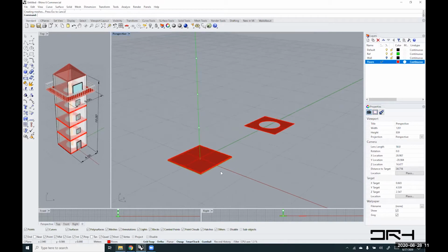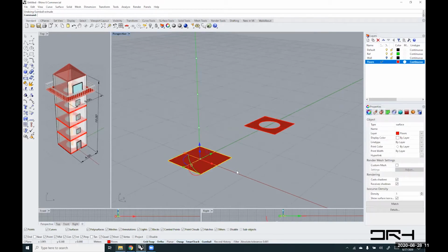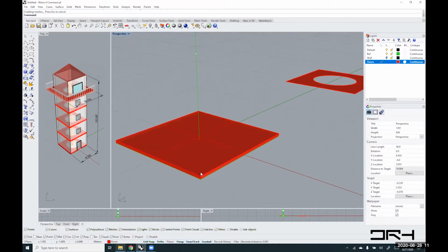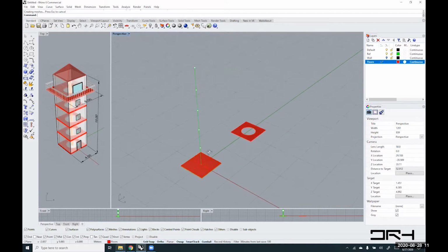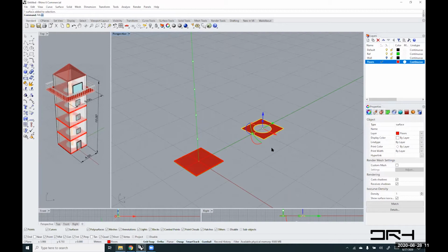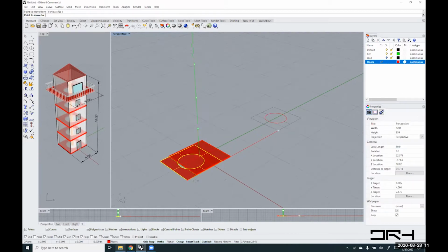Now I'm going to create it with Extrude Surface. Undo, and you can just click on it and type Extrude Surface. It will ask you what kind of thickness you want, if you want both sides, if you want it to be solid, if you want to delete your input, in this case, yes, and if you want to extrude it to some boundary surface. So there are lots of options there. But what I care about is 0.1 is the distance that I want, and that created the thickness. Same thing as we did with the Gumball, really. Now I'll just move this using the move command back to the corner here.